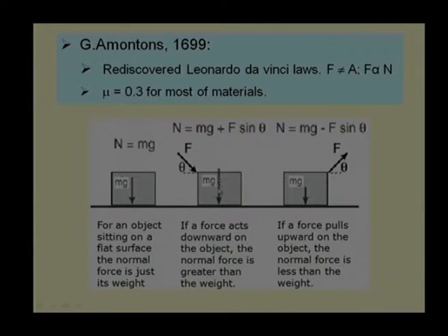You say that whatever the weight was there, in addition to that friction force, this tangential force is creating a component to resist. That means this F sin theta is an additional component, and it is increasing the friction force. In the third case, it is subtracting: we are trying to pull up, where one component is vertical, acting against the gravity force. That means it is helping us, and the friction force will be reduced in this case.